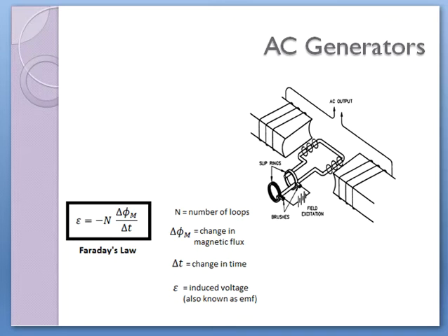Now, through this demonstration, we can see here that there is a winding. This winding is the field winding. When it is rotating, a voltage is developed across the terminals of the stator winding. So, the EMF that is induced here, we can see, is equal to minus N d phi by dt. N is the number of turns, and the minus sign is because of Lenz's law, which says that the cause and effect are opposite to each other.